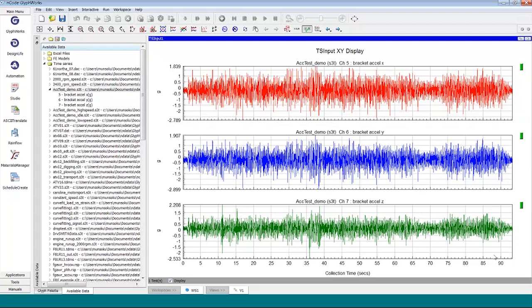That engine vibration and road vibration is characterized or understood by using an accelerometer, in this case an X, Y, and Z triaxial accelerometer in this location. This would be at, say, the bracket that holds the lighting assembly on. So this is G's versus time, and this will help us understand how severe the measured vibration environment is.